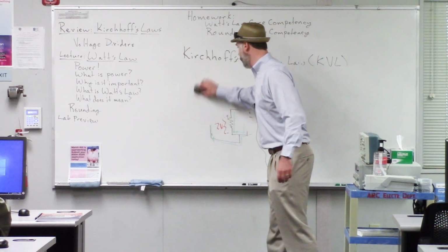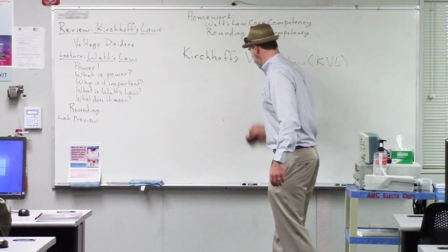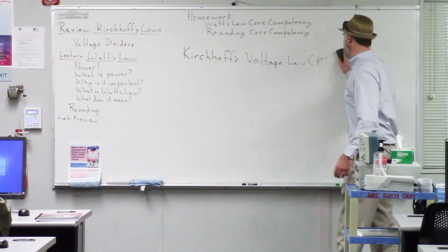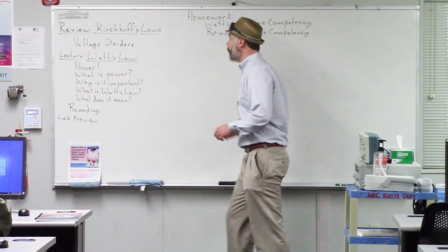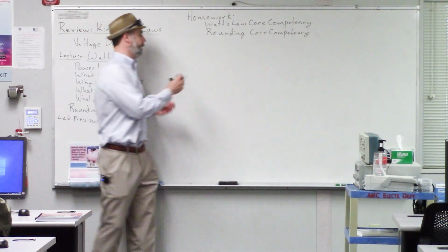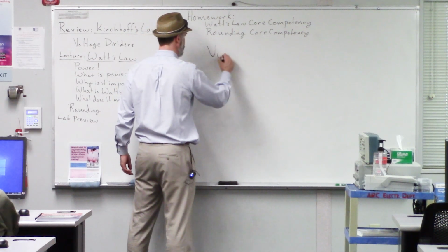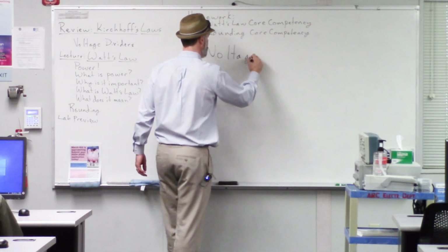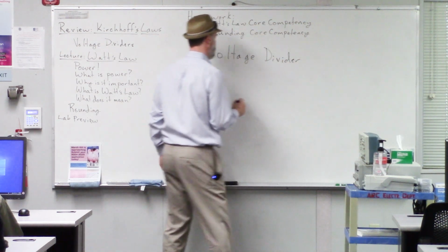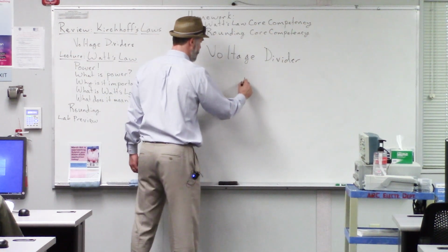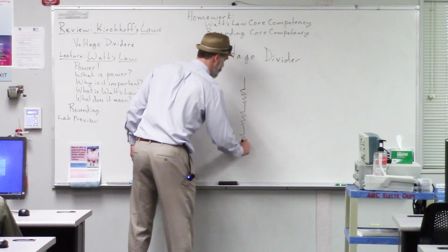So then, let's briefly review voltage dividers. So a voltage divider does just what it sounds like. It takes a power supply, so this is a voltage divider, really it takes a large voltage and it divides it among several resistors. So a voltage divider is nothing more than 2 or more resistors in series.